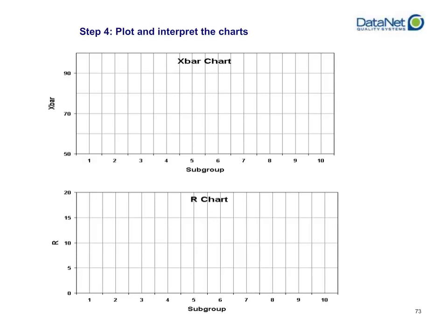Something to note, just to take care with when you're doing this by hand, you probably want to use a ruler, you probably want to use a pencil, and very important, make sure your scaling makes sense, because if your scaling is off, it's going to be really hard for you to draw each one of your data points. So just take care to make sure that your drawings are actually going to be able to fit in the charts that you have available to you, and that the scaling is consistent. We did provide to you in the SPC Fundamentals training manual a set of charts that give you a pretty good scaling already there for you, but do take care not to squish the data too tightly.